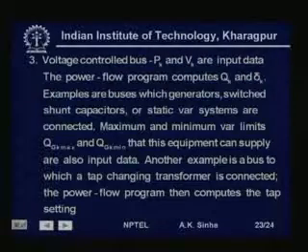The main reason for this is that at these bus bars, since we have reactive power control available, we try to keep the voltage controlled or the voltage magnitude at some specified value.